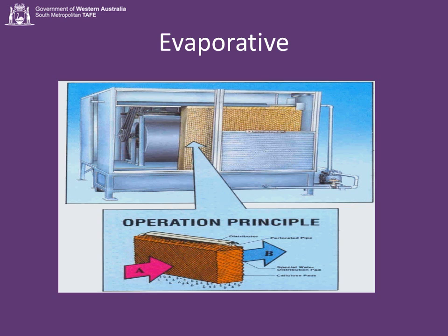As each water molecule goes from the liquid state into the vapor state, it has to absorb enough energy to satisfy the latent heat of evaporation. The only place it can absorb that energy is from the surroundings. So basically, as each molecule of water goes from the liquid state to the vapor state, the surroundings are cooled down. The temperature goes down, so it cools.